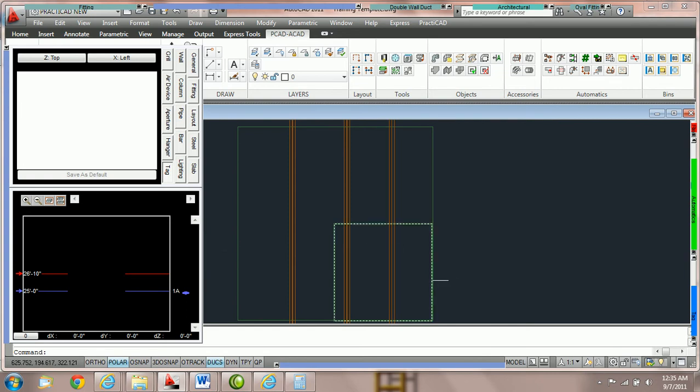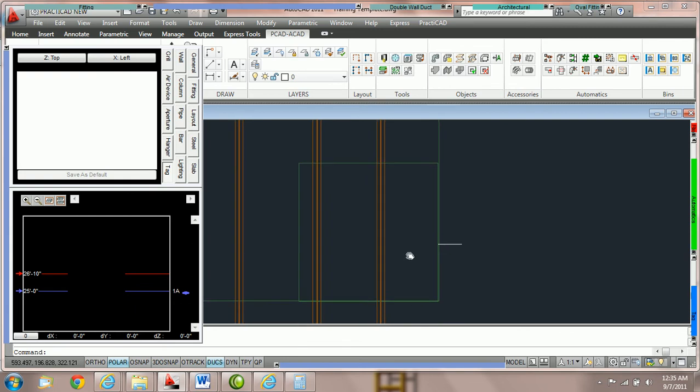In this tutorial, we're going to route duct in this section here. This section we have marked as 1A, and we have set it to be our new relative bottom by just clicking here and setting the bottom to be blue. So we're going to use the top of this slab, which, if you click on it, is at 25 foot in absolute elevation. That's going to be our relative bottom.